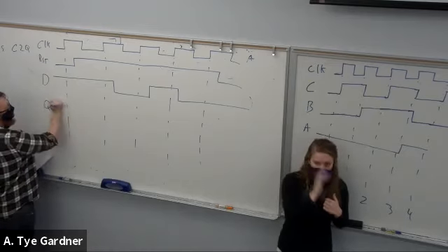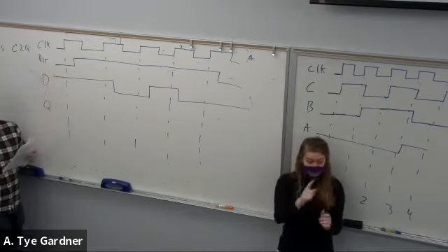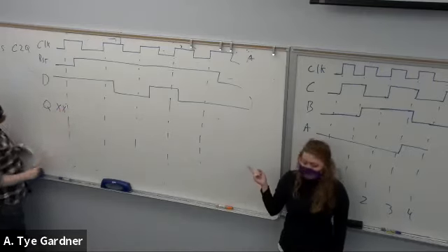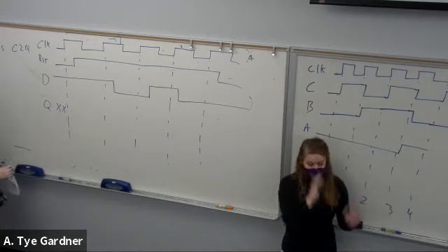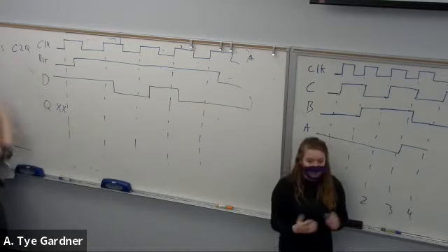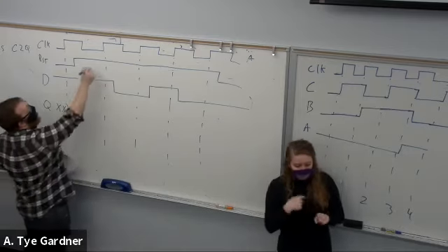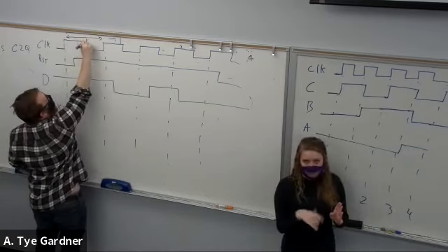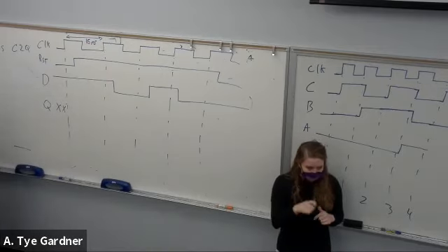Or you can admit that, look, until this first rising edge clock, I just don't know. Unknown, X. Don't know. Okay. Now, I said that the clock to Q is 4 nanoseconds, so then I have to tell you something like, well, the clock period is 16 nanoseconds, so that we have some sense of time scale, right?